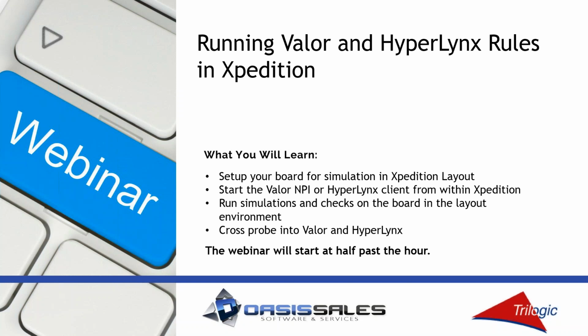So we'll be able to run simulations from predefined checks on the board, so we can define voltage drop or PI effects. We can look for certain causes of EMI issues, and then we can also look for assembly or manufacturing checks with the Valor NPI tool. And we'll be able to review those hazards and cross-probe directly into the layout tool where those hazards exist, all in Xpedition Layout. So this can be a very powerful and easy to use solution.